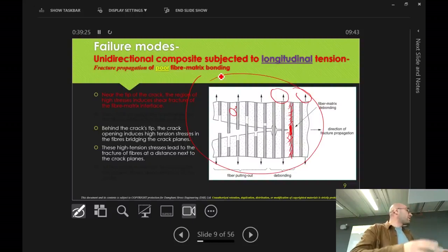So that's why when you do high performance manufacturing of composites, you've got the hat, you've got everything, as if you're a surgeon. Exactly. So it happens in the clean room, and the technicians would be wearing all of that, and then potentially they use robots to cut the plies. So the composites are very sensitive, particularly for aerospace and space shuttles and space applications. The moment you've got a tiny bit of dust in it, it causes delamination.